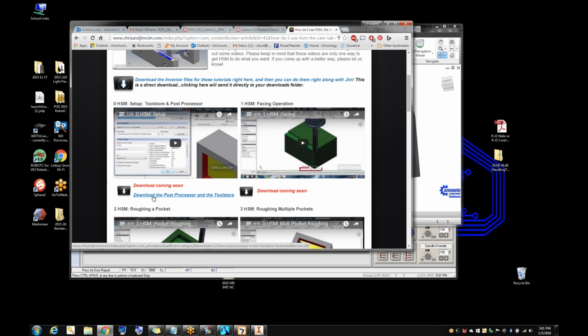And I guess that's just one of the constraints you put on the project. You tell them from the get-go that they have to be able to machine it all with a 1/2 inch. And when you look back at that original diagram, it's in there. You get to tell them what the minimum inside radius is, and with a 1/2-inch tool, my minimum inside radius is a 1/4 of an inch. As long as they at least use that, then they shouldn't have any problems with my tools. It just saves a lot of time.